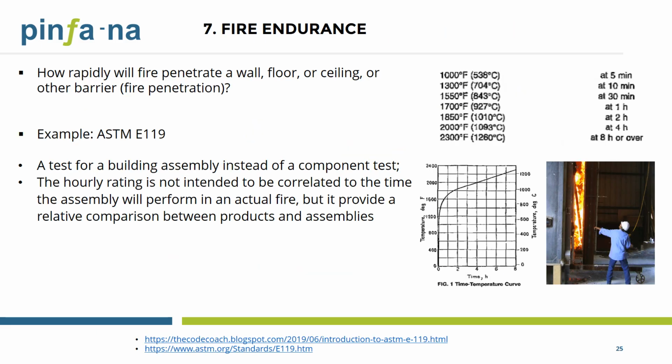Fire endurance. For a fully developed fire scenario, one of the concerns would be how rapidly the fire penetrates the wall, floor, or ceiling that separate the rooms. The ASTM E119 test is used to determine the duration for which a building assembly is able to contain a fire, retain structural integrity, or both during a predetermined fire exposure in the test. This is a large-scale test with the exposed area of the test assembly to the furnace measured as large as 10 foot wide and 10 foot high.